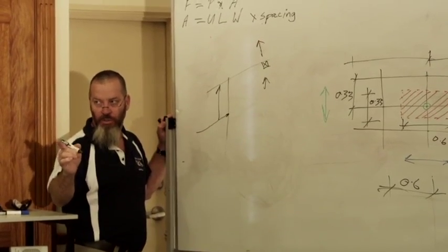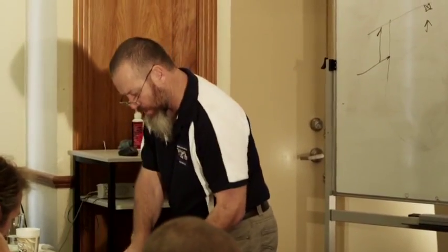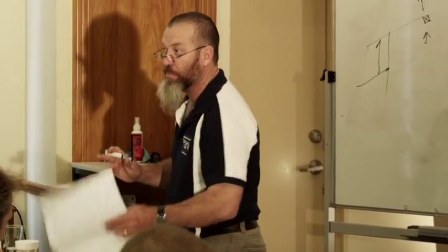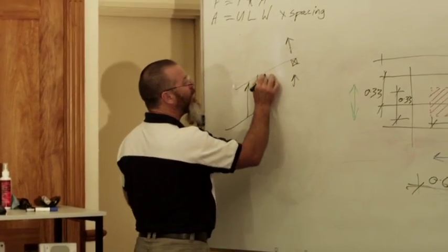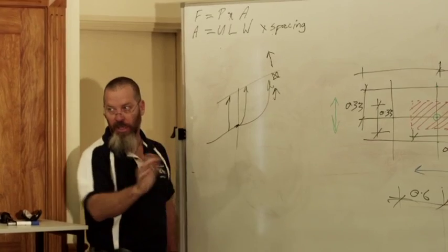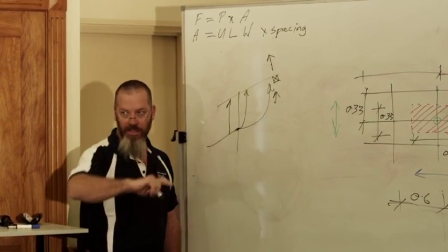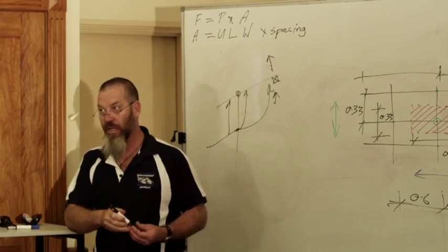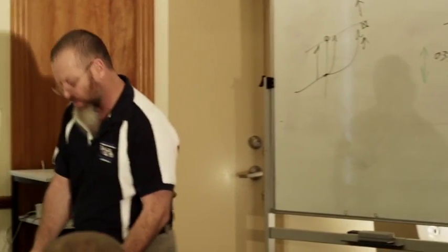Table 9.22, it said veranda beams, rafters to beams, lintel ring beams or veranda beams. Beams, not walls. So the wind can get underneath this one and up underneath this, either side of that connection. So using this connection will far exceed the requirements of the connection that'll actually work there. It's a waste of money using that connection. And you'll probably find most of them are not appropriate anyway.